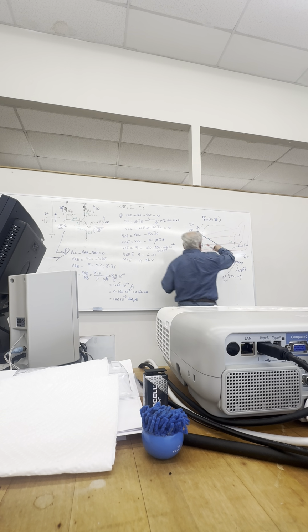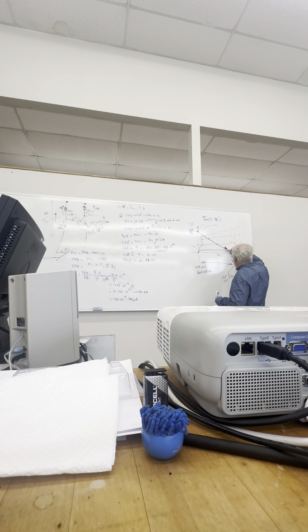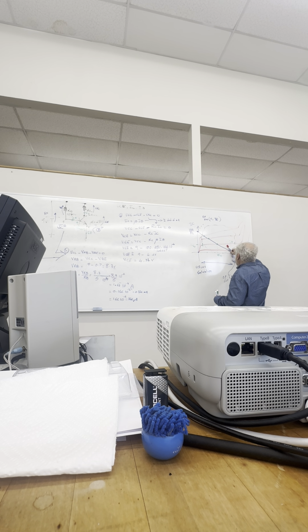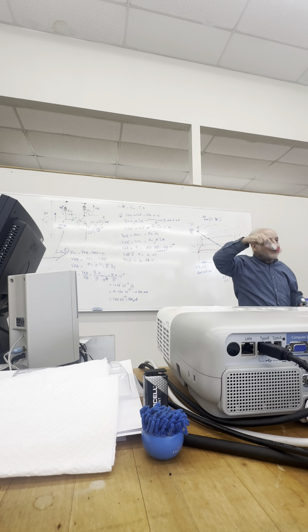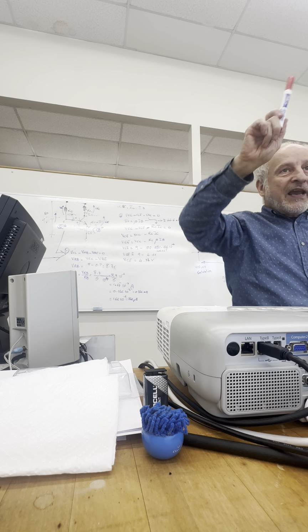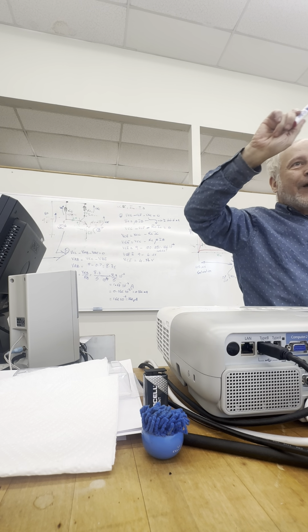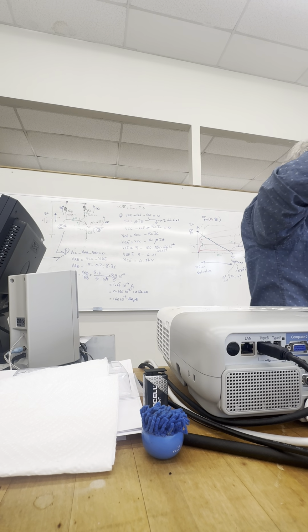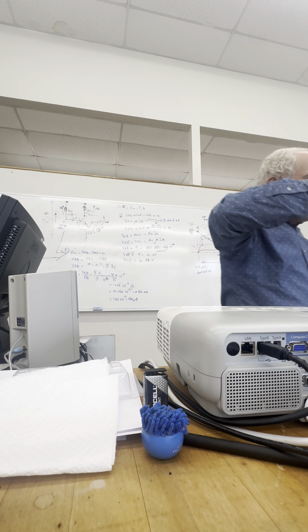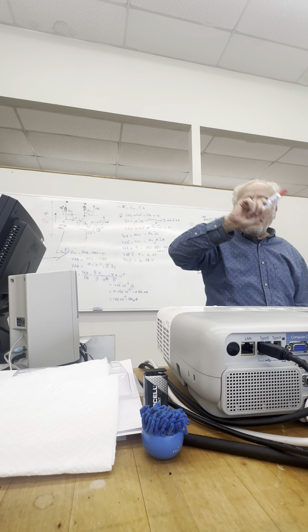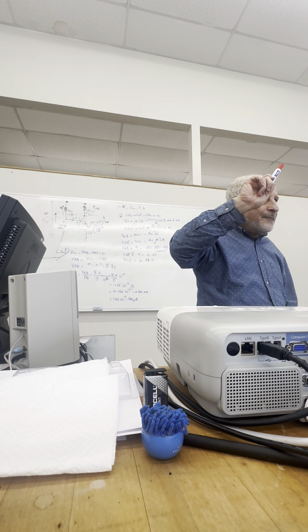Now, if I had RC as a potentiometer, then I can have a load line that can do what? From this point, does what? Does this, because this ratio here will change. VCC stays the same, but RC goes up or down. Then I can play with the load line. You with me so far? It's where engineering comes in. This is why we do these things, so we can manipulate where we want to be. You with me so far?